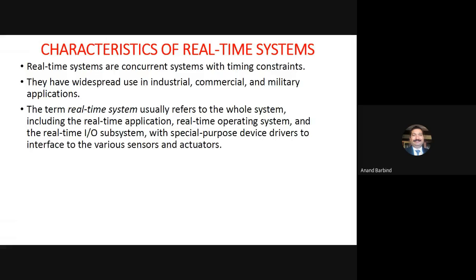Sometimes these particular actions are very critical. For example, there is likely to be an overflow if the level sensor detects a certain level, and based on that, if a certain actuator output is to be generated, then the response time of the system should be very quick, and it should give a signal to the actuator to close a certain valve or shut off some pump, so that the level will not cross the maximum limit.